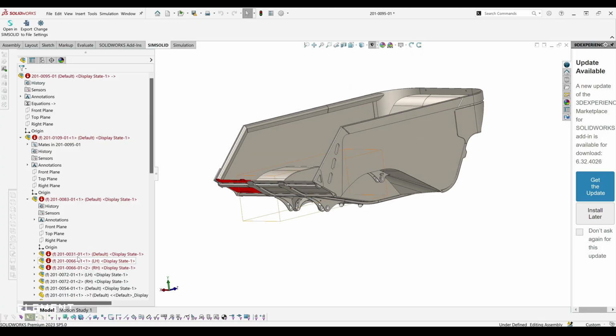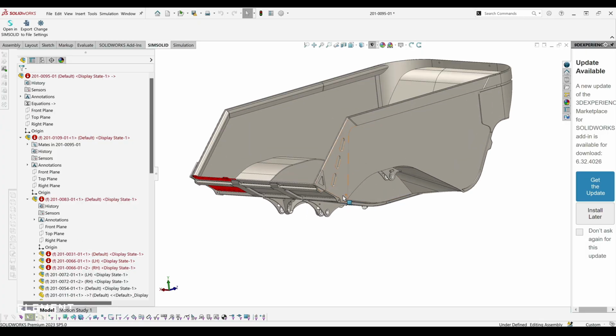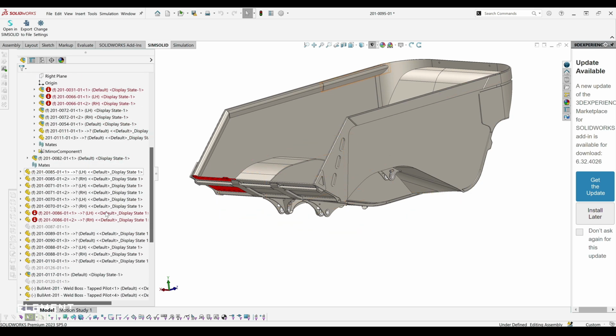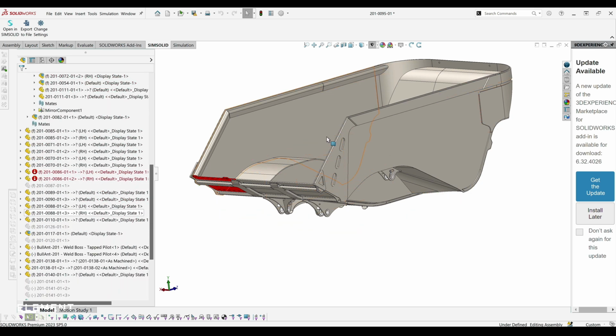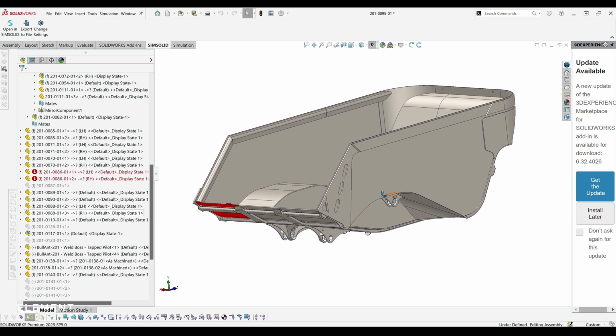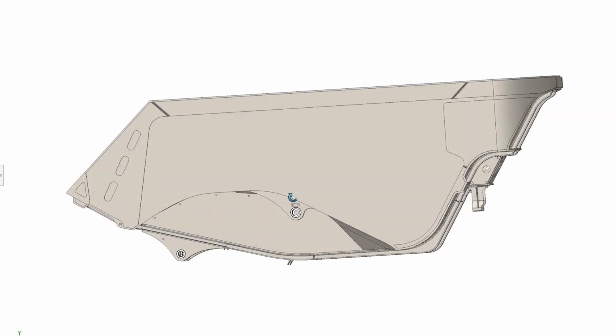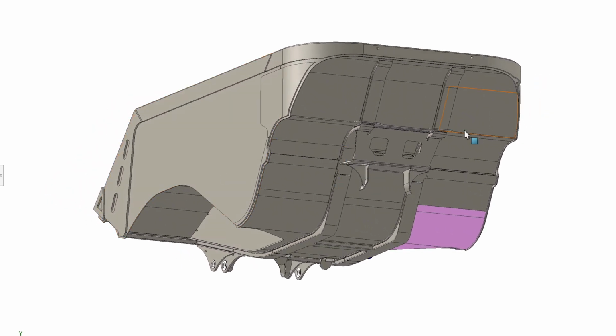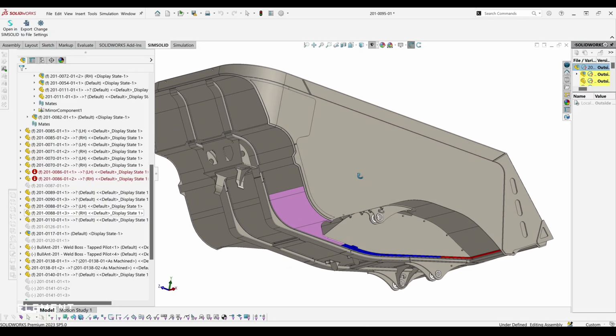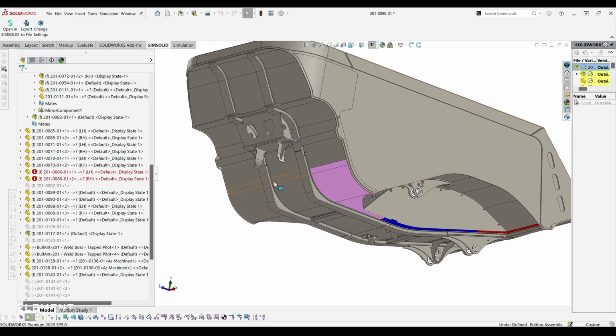The model we've got up here is one from years and years ago, maybe 2012, 2014-ish era. This is actually an underground truck tray which we were creating at the time, and it was very successful. Myself and Frenchie, Ben, who was the first employee, Dan was the second employee for Element, went out and measured our underground truck using measuring tape and different hand tools and came up with a model. We basically simulated it using Abaqus back in the day and iteratively improved it and got rid of all the hotspots. This truck tray went on to serve thousands of hours, as far as I understand.